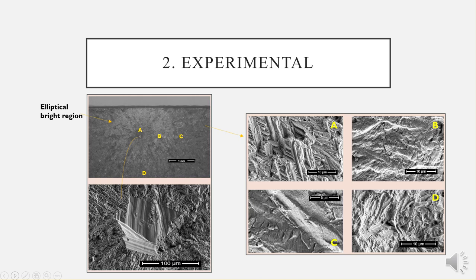This can be a consequence of the two sides of the crack crashing against each other multiple times, erasing all crack front evolution information. If we continue moving farther away from the defect, more and more striations are visible as we progressively get out of the bright region, as shown in figure C.